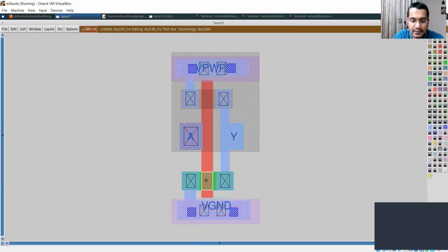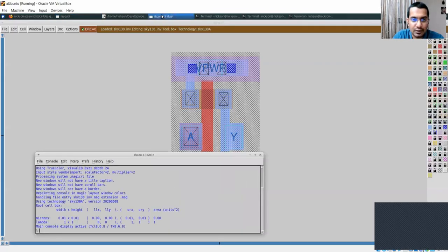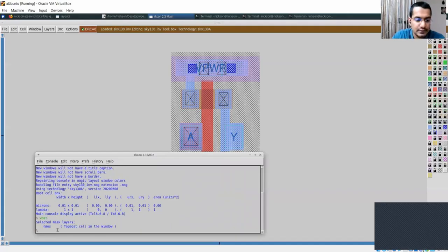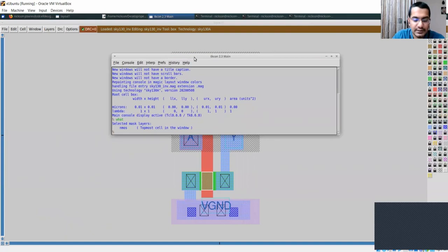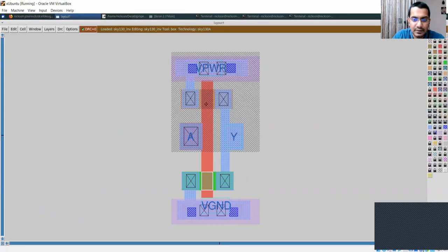The next step is to create the contact holes. So for example, if we decide that we want to create some contact holes over here, let's say somewhere over here and somewhere over here, we do so by drilling some contact holes. Drilling the contact holes is something like you take a pin and create a contact hole over here. In a broader language, but for a CMOS fabrication process, there are various steps to do it, and we use the same photolithography step to do the contact holes. So this is how we do it.